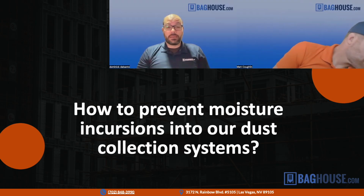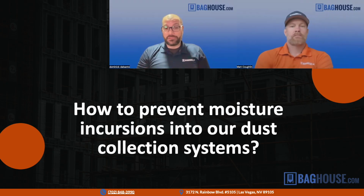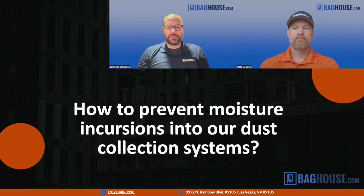So moisture in your baghouse is like the ultimate enemy. So you want to keep it out at all costs. If you have to live with it, then you need to do a couple of things to make sure it doesn't mess up your life. So the first thing is if you have a process where there's some kind of moisture, steam, things like that, you have to design the pickup of the dust collector pickup very carefully.